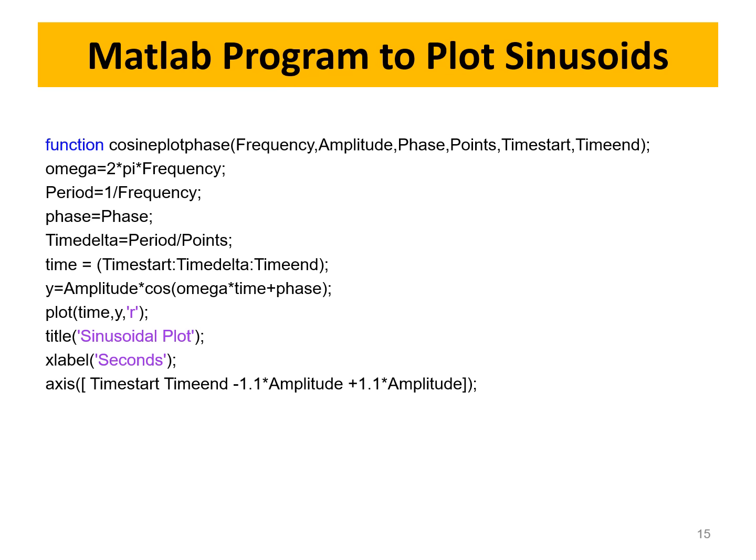Now remember, MATLAB is case sensitive. So if you have frequencies like this with a capital F, make sure that the first one is a capital letter. Alrighty, so just to make sure that we know what we are talking about here, you need to comment this. You don't need that, and it should be green, right? So that it's all green. That does not need to be there.